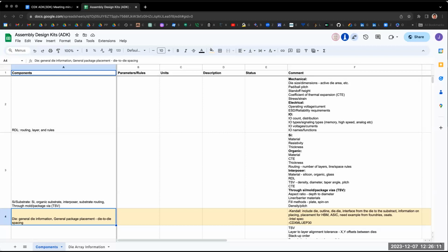So the first thing is just your basic assembly rules, right? So these are the rules so you can build the interconnect, right? Place the vias, the through silicon vias, the bumps, the micro bumps, whatever, and route those. Now there are additional, and I believe the Synopsys format does support that. But one of the issues that Intel had, and we have as well, and I imagine Cadence does, I talked to Mike, he has the same concerns. There's other rules that you have to worry about.